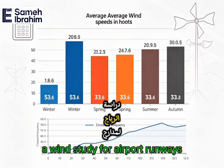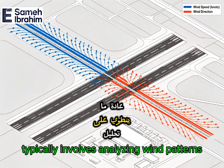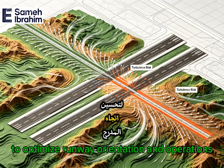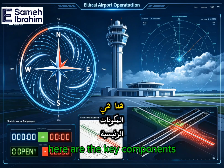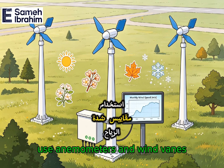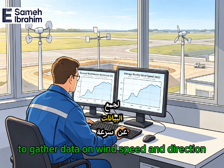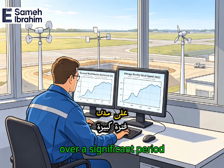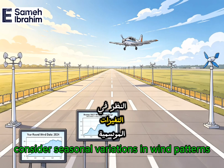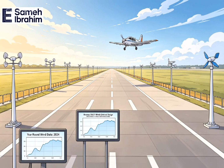B. A wind study for airport runways typically involves analyzing wind patterns, speeds, and directions to optimize runway orientation and operations. Here are the key components. B1. Wind data collection. Use anemometers and wind vanes to gather data on wind speed and direction over a significant period, usually a year. Consider seasonal variations in wind patterns.